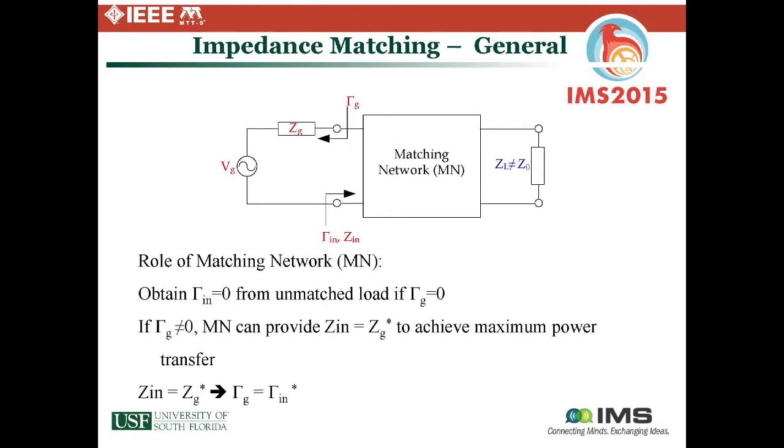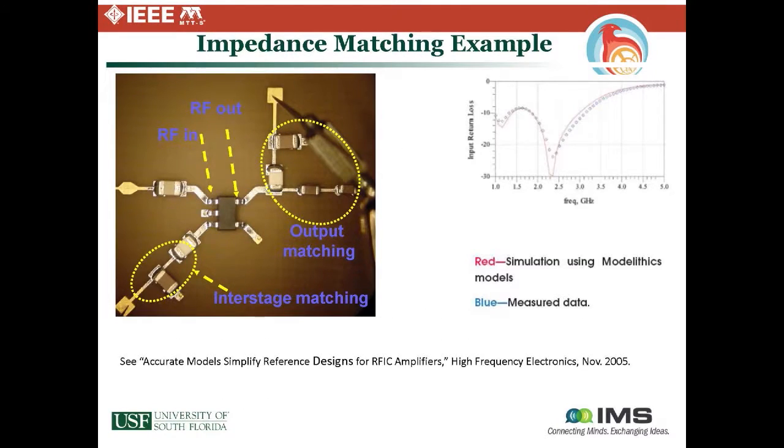Here's just an example of a PCB board match. A customer asked us to take an LNA surface mount amplifier that had a reference board with a 2 gigahertz matching circuit already built up on it, but our customer wanted to use it at 2.3 gigahertz.